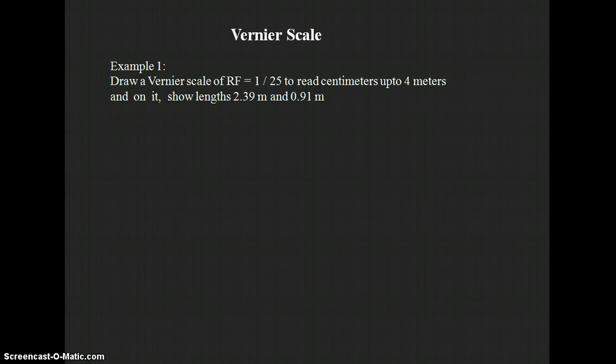So now we discuss Vernier scale, a simple example. The problem is given as: draw a Vernier scale of representative factor 1 by 25 to read centimeters up to 4 meters, and show the lengths 2.39 meters and 0.91 meters. So by constructing a Vernier scale, we need to represent these two dimensional values on the Vernier scale.